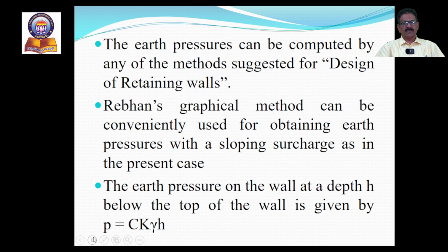Now coming to the design of this well steining, that is in the form of a retaining wall. The earth pressures can be computed by any of the methods suggested for design of retaining walls. So this is similar to the design of retaining walls. The same concept we are going to apply for the design of well steining. Let us imagine, of course, the well is in a circular shape. Let us imagine a masonry wall as a retaining wall. So whatever procedure we are following for the design of retaining wall, the same can be applied for this case also.